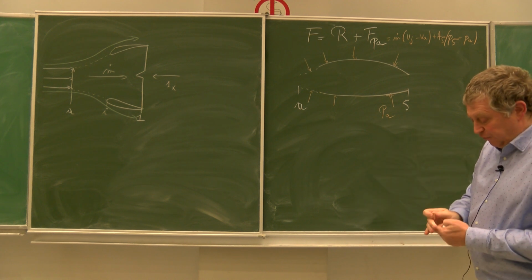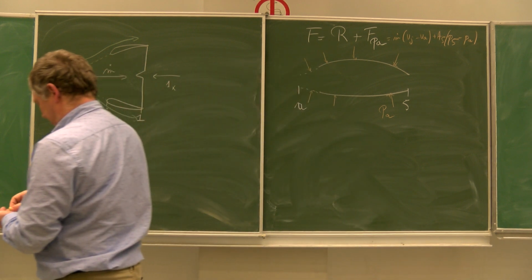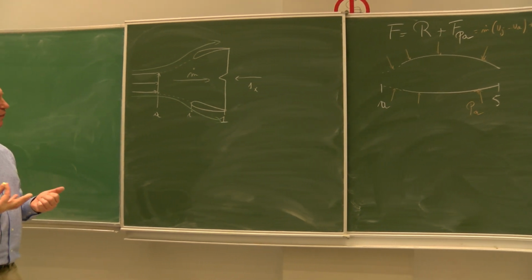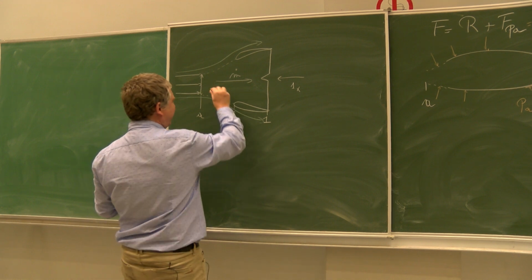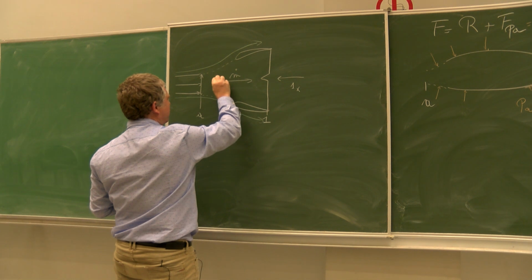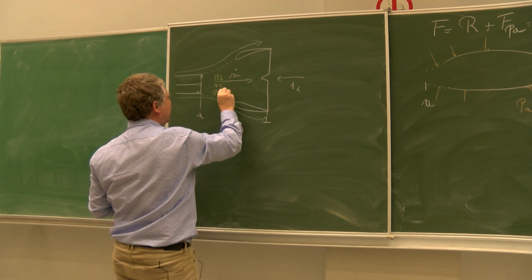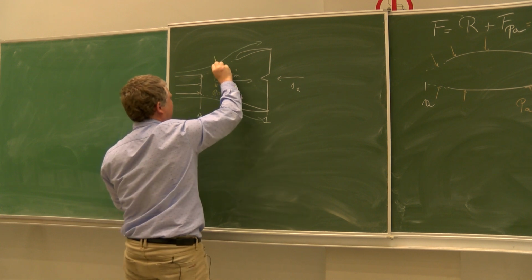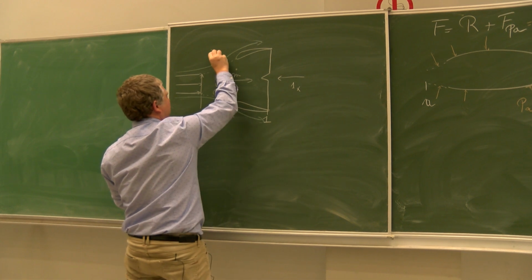But if we look at what we discussed yesterday, we see that through the shape of the external tube, or the stream tube, what do we have? If you consider the part between A and I, here you have a decrease of the speed, a decrease of the Mach number, an increase of the static pressure, and that means that the pressure here is larger than PA.